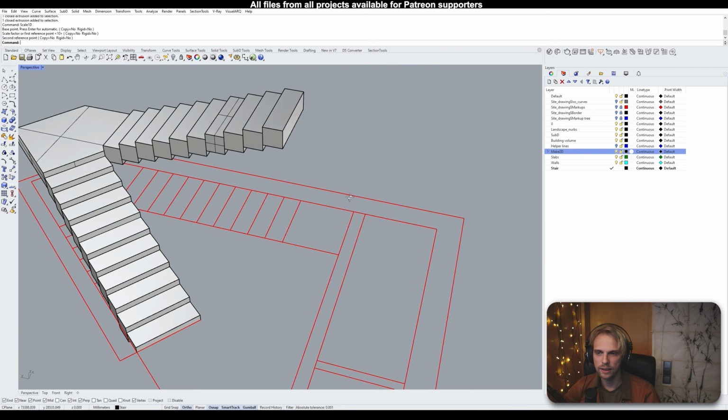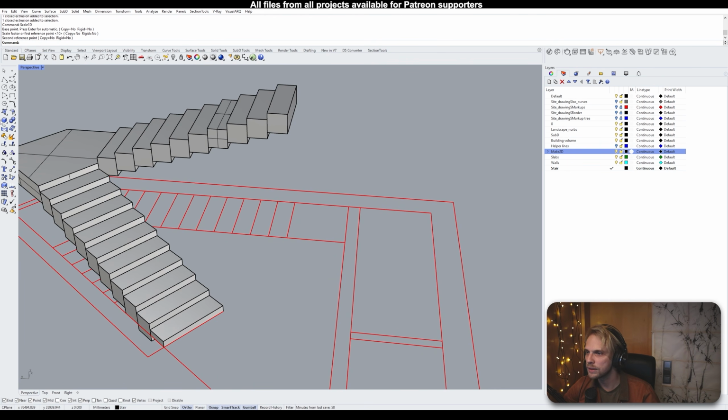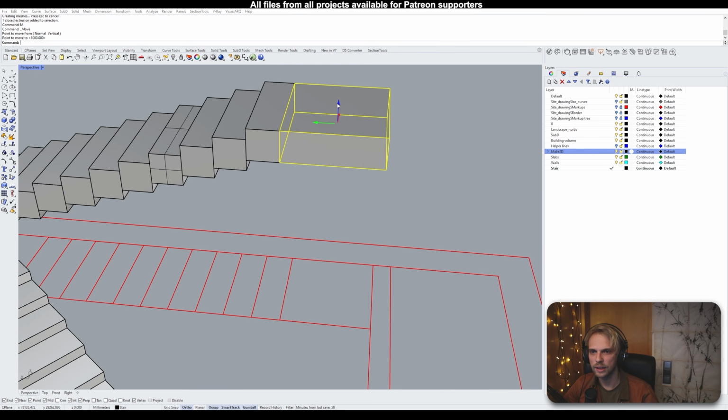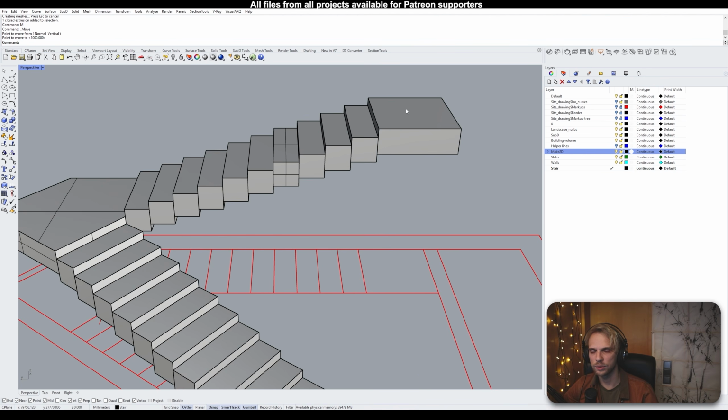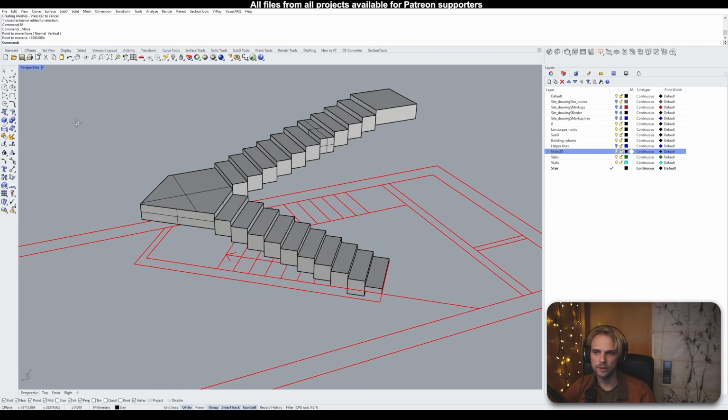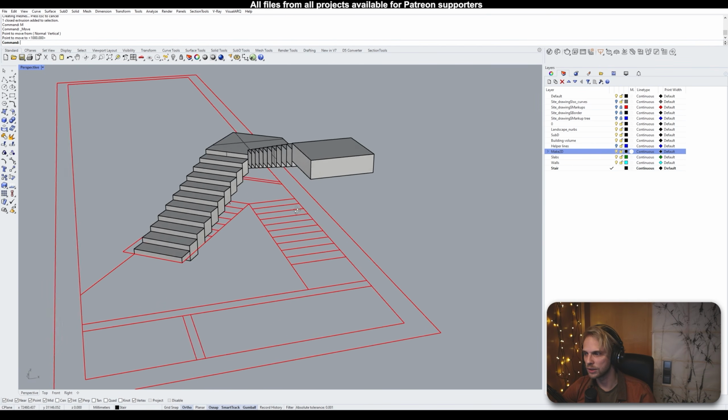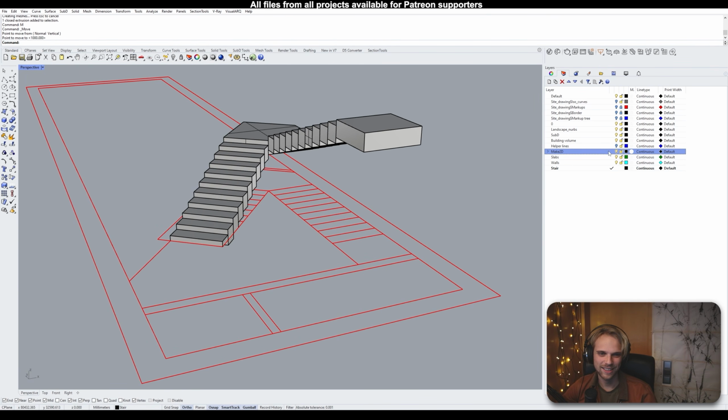We don't need the lines anymore, kinda. We'll still need this. I should add it. So I'm just going to create a box, and now it was 100 millimeters plus 200. So let's do a 300 millimeter box in height. First of all, I'll just move it here, and then I'll jump 100 millimeters more, so it's one additional step. We have ourselves this monolithic looking Minecraft staircase.